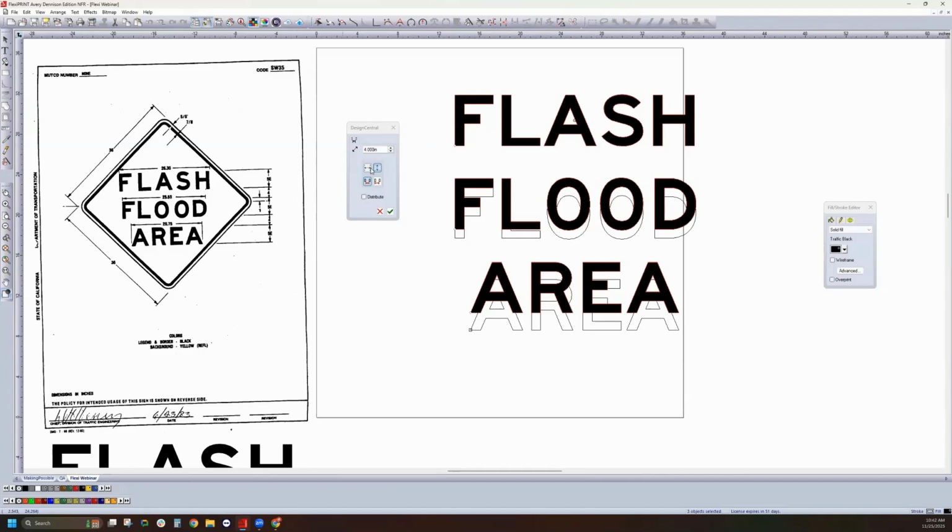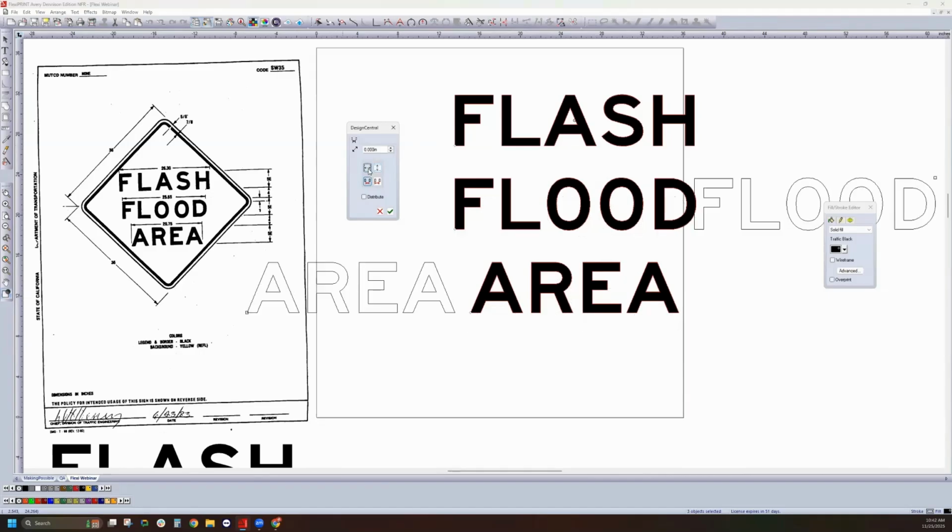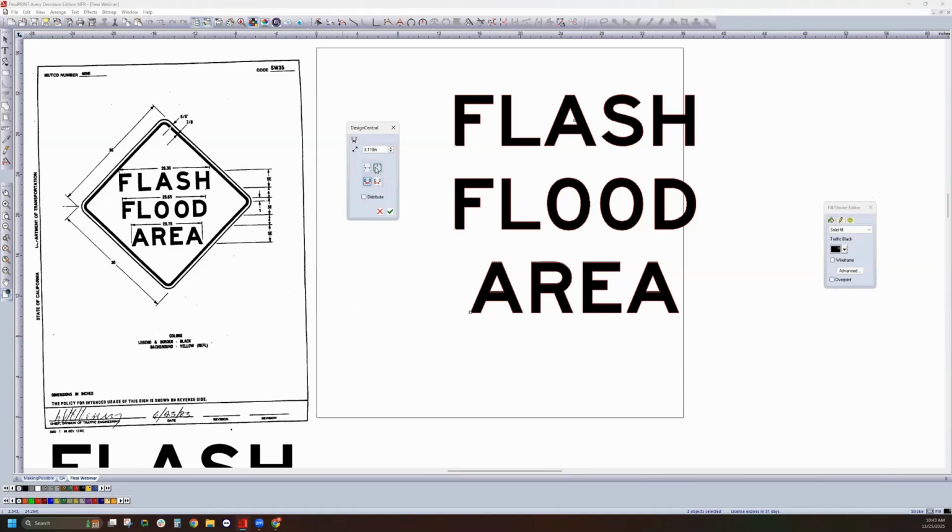Before I do that, I'm just going to point out that we have a horizontal spacing option. So if that was checked, we'd get something that looked like that. We obviously want the vertical. The next thing down is we have an end to beginning and a beginning to beginning. So that's just adjusting where the space measures from. So it either does the left side or the top, depending on if you're doing horizontal or vertical.